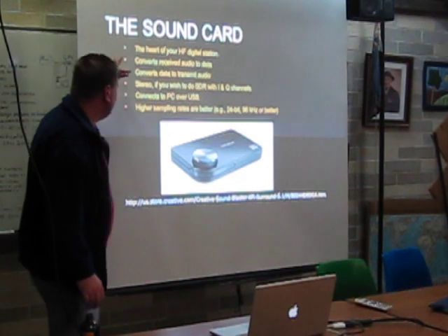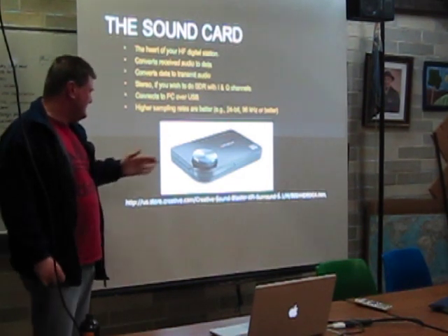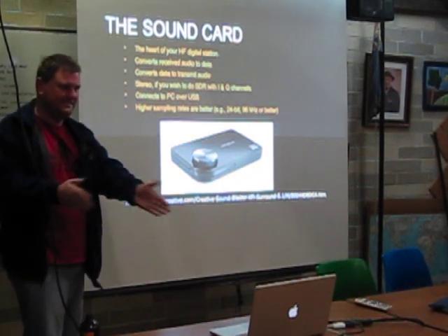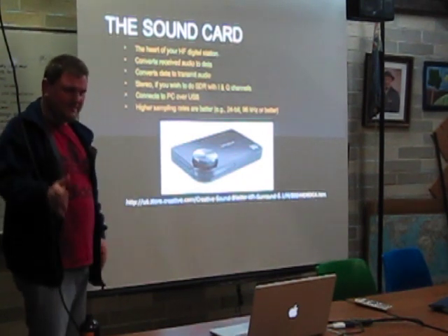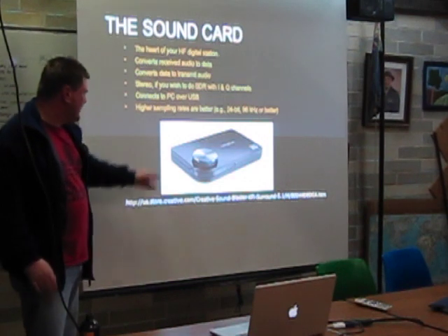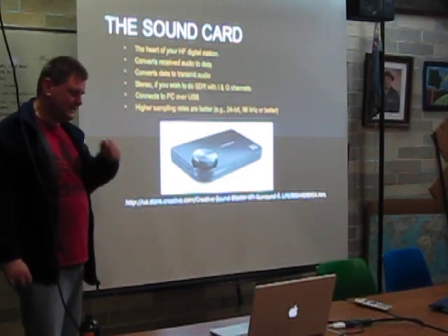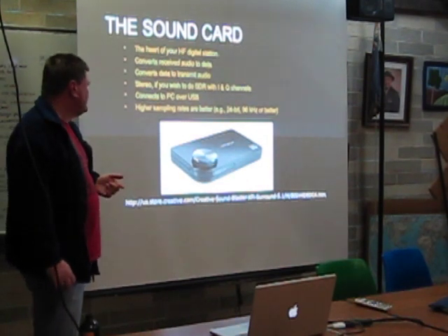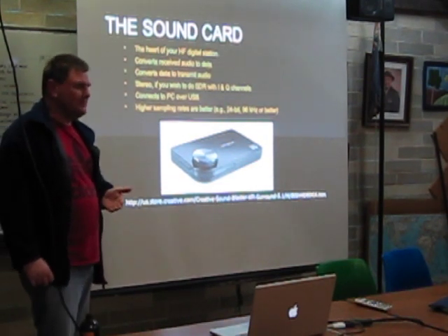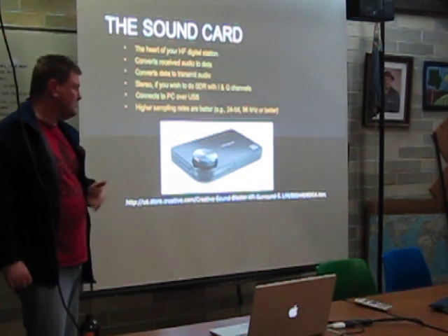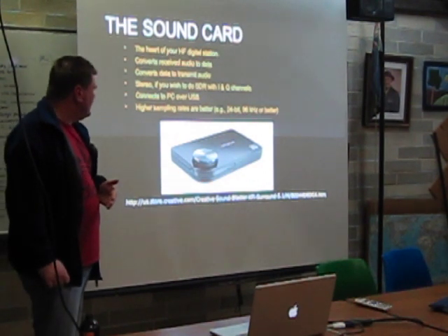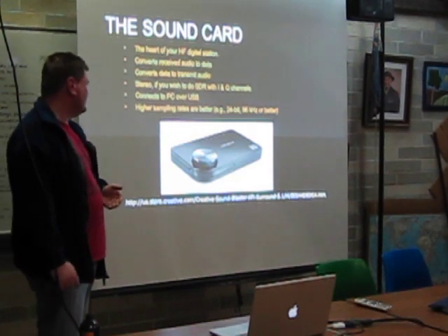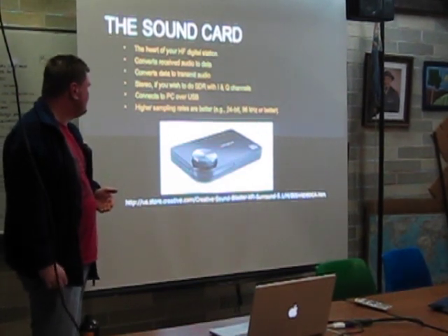So with the sound card, basically the computer is digital and the radio is analog, so you need to move from the analog world into the digital world. And that's what a sound card does. It basically has inside an analog to digital converter. So you want a reasonable quality one in order to preserve the quality of the signal. Most sound cards are usually quite good enough.